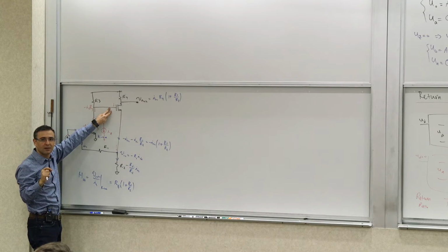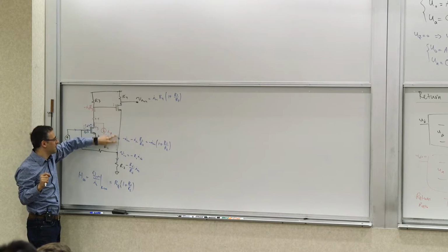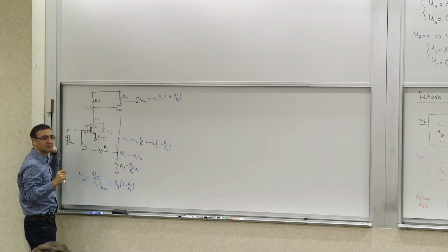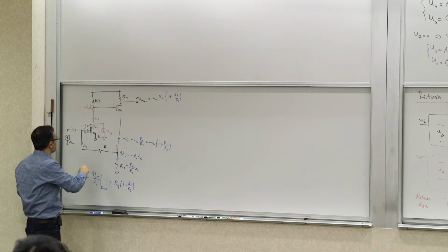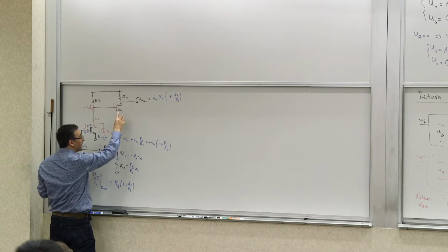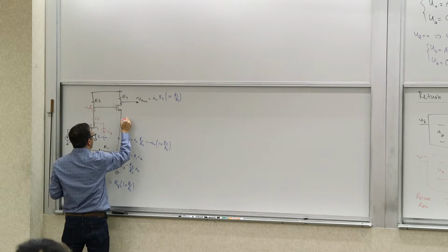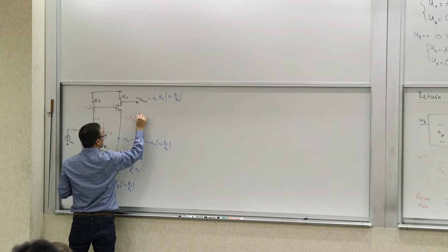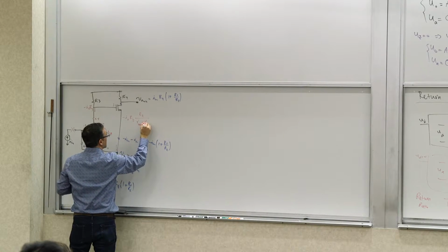We have a follower, right? What do we have in this model? The easiest way to think about this is the T model, right? You have an RM and R2. There's no current flowing in this direction. So by the way, when we are doing the return ratio, this is gone. So this is gone for return ratio. Okay? So there's no current flowing in this direction, right? So it would be a resistive divider between R2 and RM. It's a source follower. So this voltage would be IX R3 times R2 over RM plus R2.